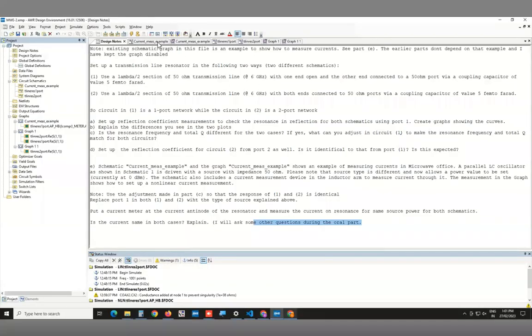Okay, slightly more difficult than the first one, but still, if you had just read the things and not made very obvious mistakes. So what were the mistakes here? The first mistake was choosing the wrong measurement to find the resonance. The second was not realizing that one had to zoom in to the frequency of the resonance to find the signal properly. And that was it. And because those things were not done, everything else didn't make any sense at all, because you couldn't do any of the next steps.